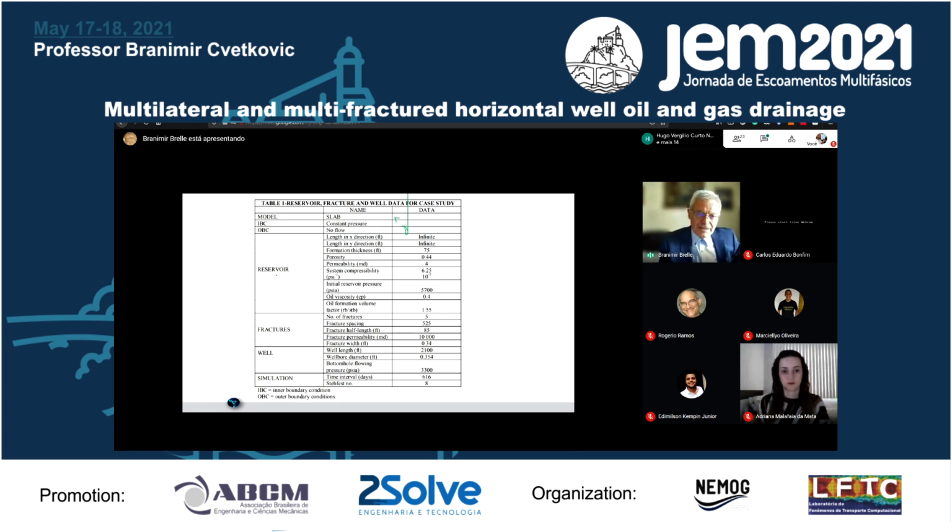So then we have here reservoir length in x and y direction. Usually I'm using a Cartesian box model for that. Formation thickness, porosity, permeability, compressibility of the system, initial reservoir pressure, viscosity of oil, then formation volume factor, because I want to calculate the fluid volume in the reservoir and how much fluid volume at the surface when it comes to the surface. So this is your surface volume, okay?